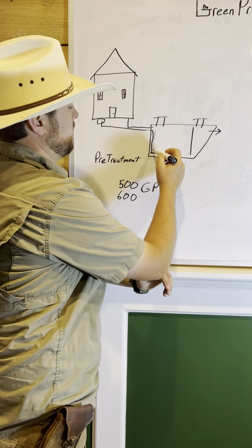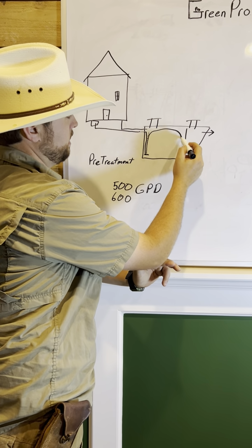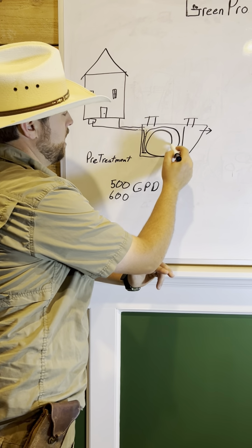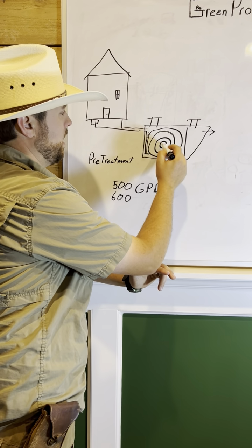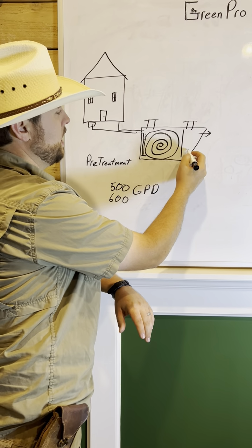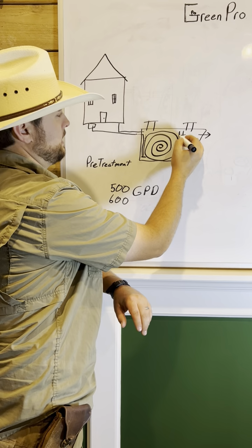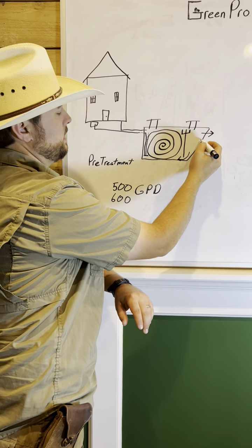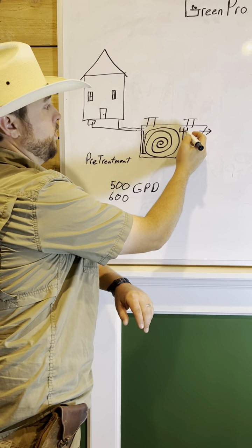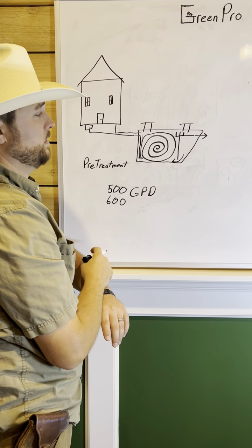This aerobic bacteria is going to break this waste down much further, as well as polish these solids, as this is creating this almost Nile River environment, I say a lot, inside of this tank, keeping it well mixed and everything broken down. This system here has a sludge return wall built in, as well as a skimmer, where we're going to skim anything that's heavy, that's floating over here, that happens to bypass the system, back over into this other side of the system.